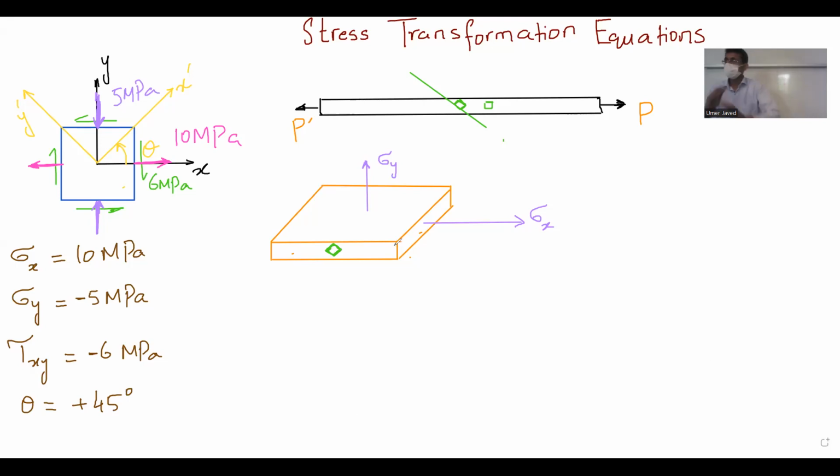Okay, that brings us to a new topic, stress transformation. What does that mean? You have a wooden stick, both of us are pulling. The wooden stick will break, in observation, at around 45, 43 or 42 degrees of angle. This means there are stresses at planes that are of extreme interest to us. We cannot just do stress is equal to F over A and feel happy about it. This means that I need a complete picture.